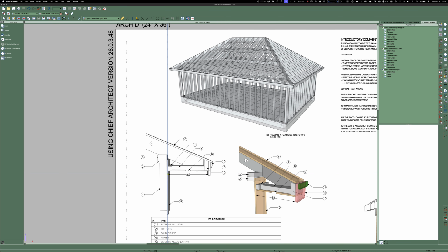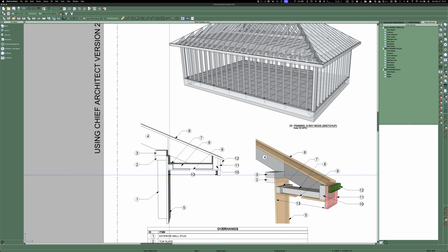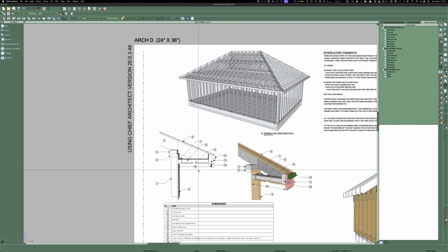But then when you turn on the overhang area, or if you dimension from framing out to the outside of subfascia, if you call this a 16-inch overhang and you dimension from framing to over this number 10, it's 15 inches. And so that means that my fascia board out here must be 1 inch, because in their software world, they go face of framing to over fascia is the overhang. And that's not true. It's not correct.